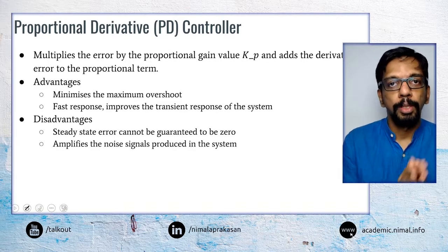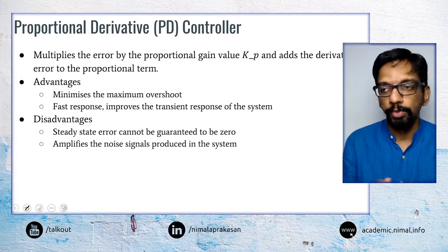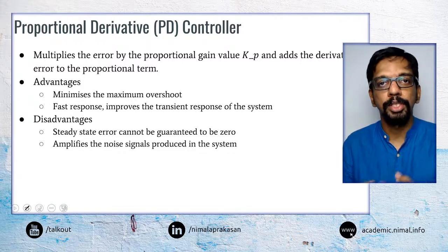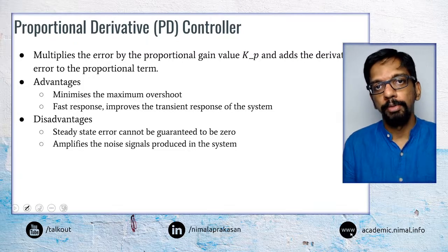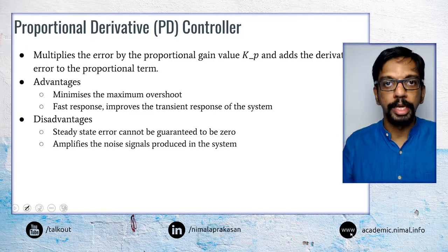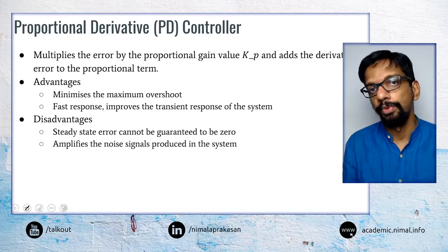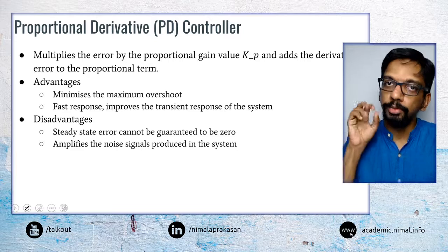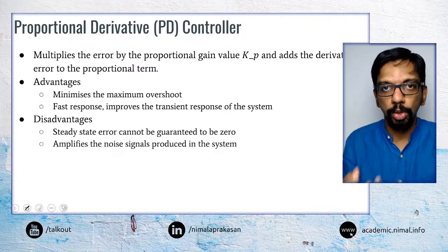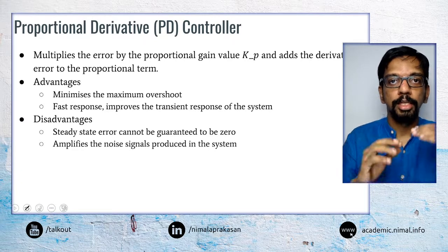Another problem that we get with the proportional component is what is called maximum overshoot, and also the ability for the system to respond quickly. So for example, we are going at a slow speed and the speed increased suddenly because of external disturbances. Somebody pushes the vehicle or something, the thing moved quickly, so we have to stop it quickly. Because the change was sudden, the integral component is not going to react quickly. But with the derivative component, what we are getting is the rate of change.